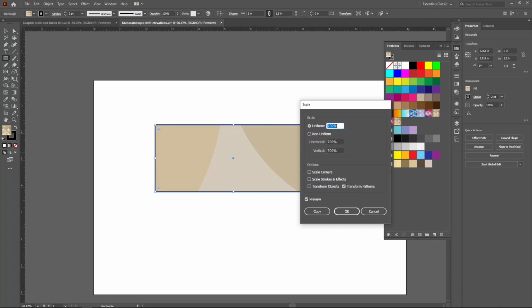Then I just need to decide what the scale is going to be. Well, I happen to know that 1 to 48 is the scale factor for reducing to 1/4 inch scale. It's just a matter of mathematics: 1/4 of an inch, there's 4 per inch, and times 12 inches per foot. Gosh, I wish we would go metric. It'd just be so much easier. But alas, we are stuck with an old imperial system. Anyway, we can type in 100 divided by 48 as the scale, and you'll come up with a number which is 2.083 or something.